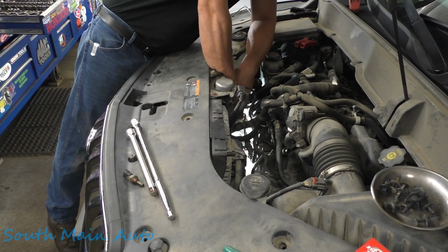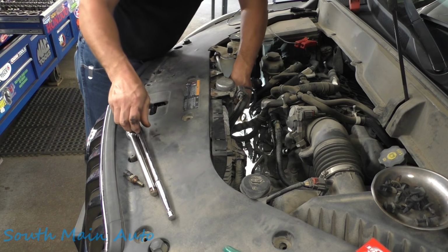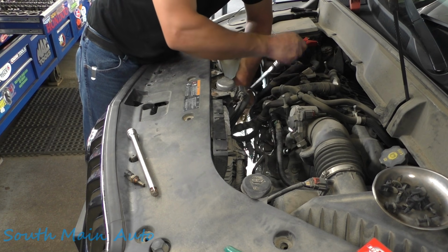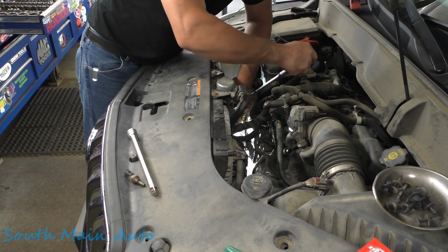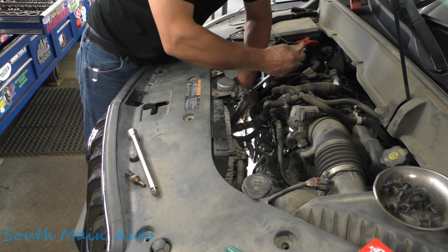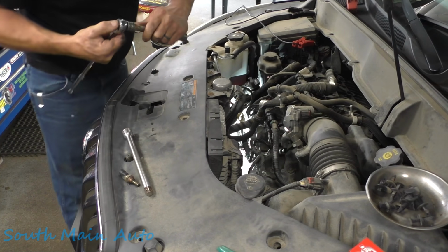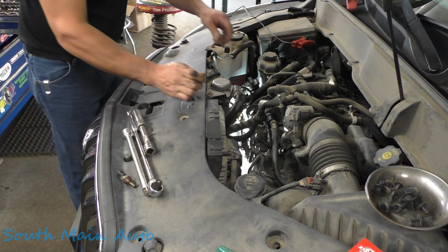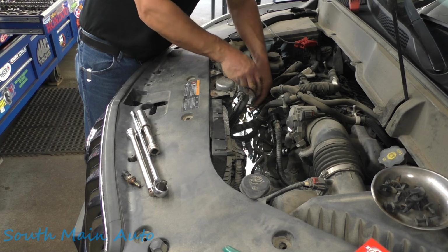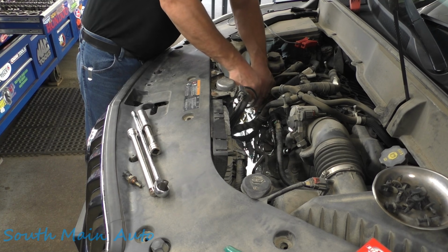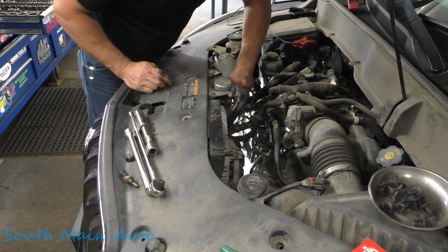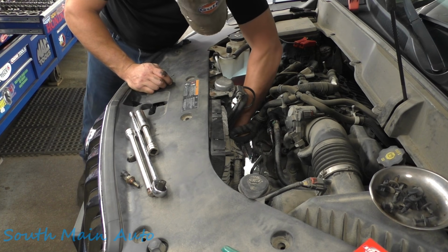And then just be careful with your socket so you don't actually break the sensor, the plastic portion of it. So don't have any unusual sideways pressure on your socket. You're going to want to torque that to factory specs. We'll come back and do that here in a minute. And it's kind of a pain to get the connector off because it does have this heat shield over it. You kind of got to pull that up, but they don't give you a lot of extra harness. And so we're just going to plug it back in here, kind of by feel.